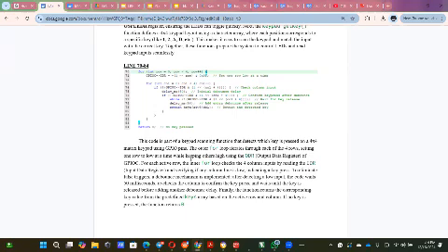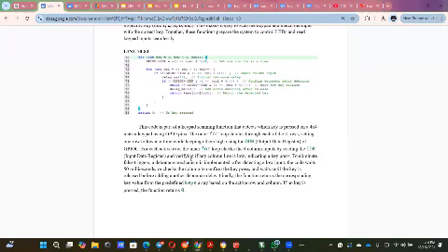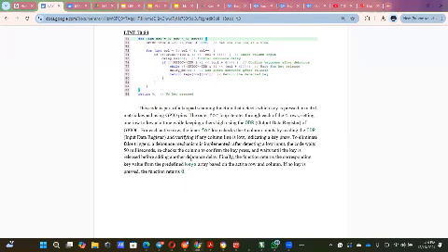For each active row, the inner for loop checks the four column inputs by reading the IDR, input data register, and verifying if any column line is low, indicating a key press.